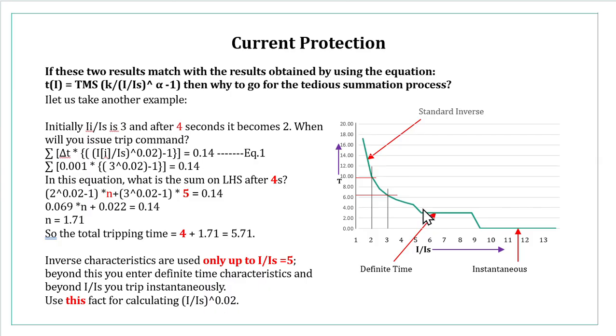So when the value is like this, something like 6 to 8 times the rated current, then you say, okay, perhaps it is starting, the motor is starting, the machine is starting. That's why it has taken such a high current. And so let the machine start. So you provide some time. In this case, you can see it is something a little more than 2 seconds. So motor will start within that time period.